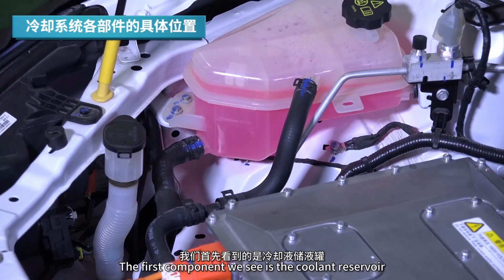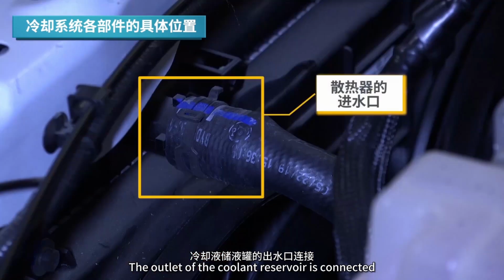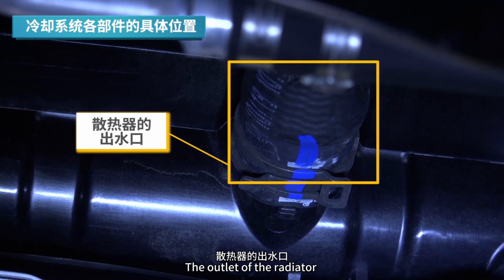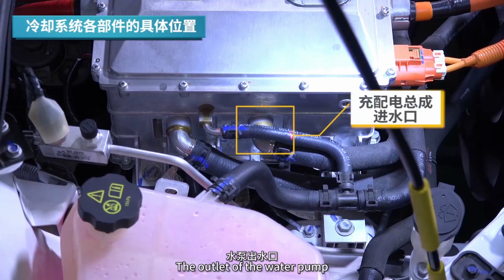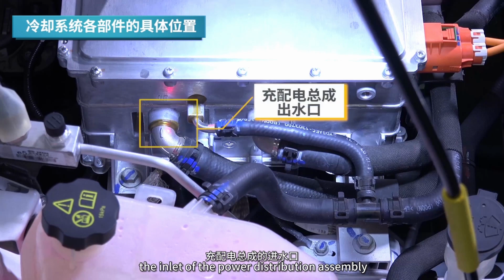The first component we see is the coolant reservoir. The outlet of the coolant reservoir is connected to the inlet of the radiator. The outlet of the radiator is connected to the inlet of the water pump. The outlet of the water pump is connected to the inlet of the power distribution assembly.